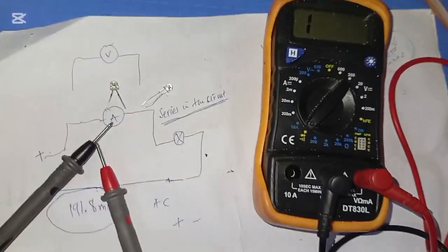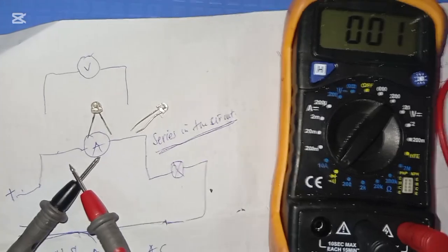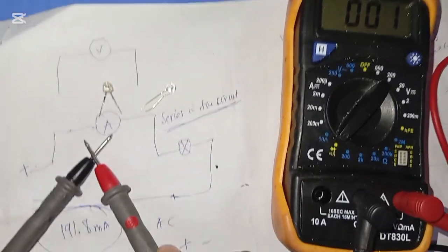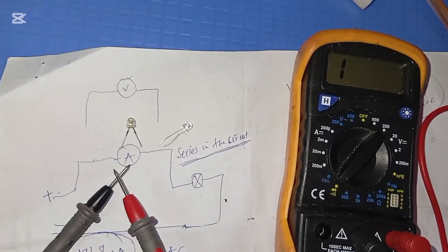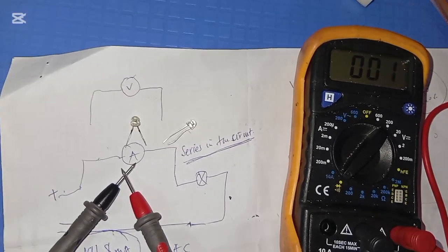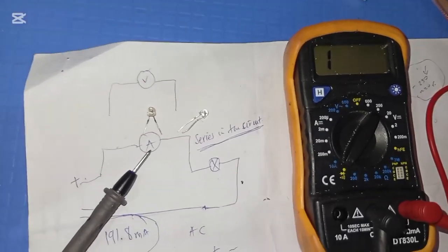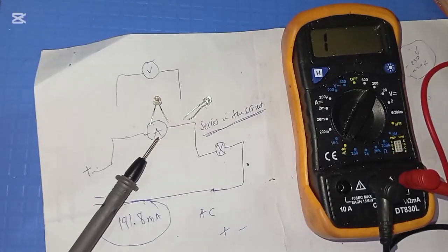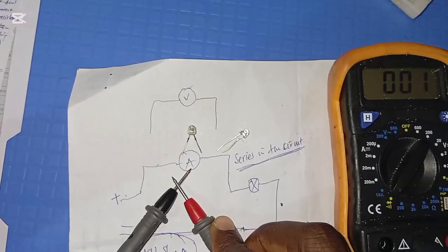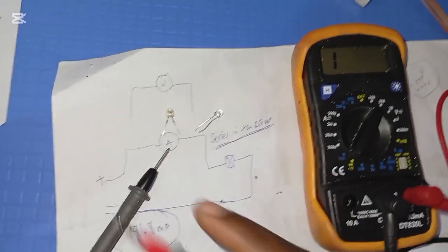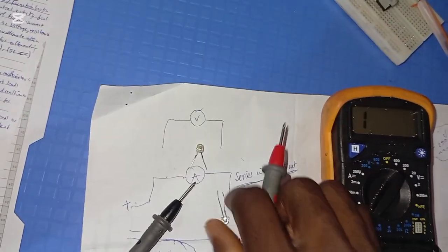Being here, let's test continuity. As you have selected, let's short here for continuity. You hear that sound? That shows that you can measure continuity at that point. Continuity normally allows us to check the circuit, if the circuit is complete. So, measure continuity. Then at the same point, we are going to test these diodes. Okay? Let's see how we can test these diodes.